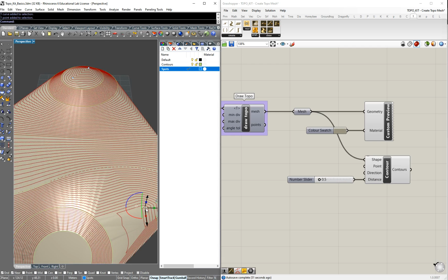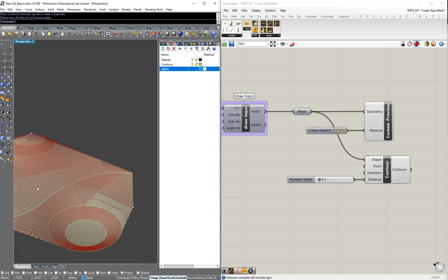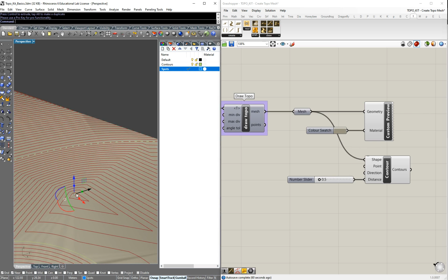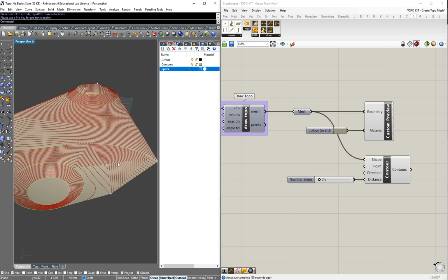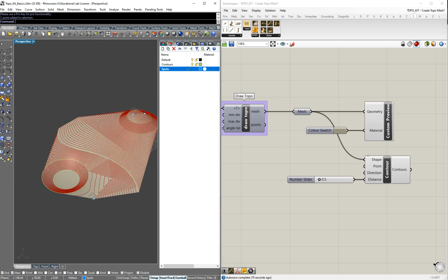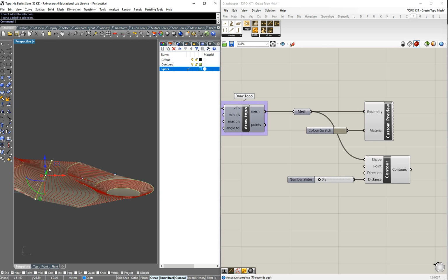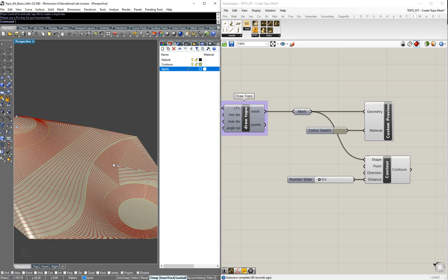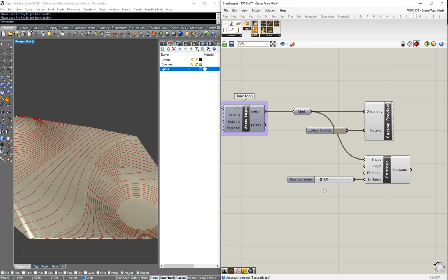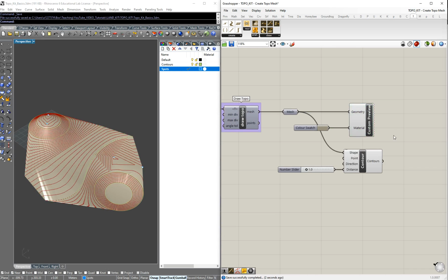them. So let's imagine what will happen if you modify and you move this back and you modify this towards the front. So as you can see here, the contours are also being changed in real time. So this gives you the possibility to modify the contour and the terrain quite easily, and generate different interesting topographic grading options. So let's move it, let's say, to 1 meter, which is a standard, or 2 meters, or whatever the value is. Let's save this.